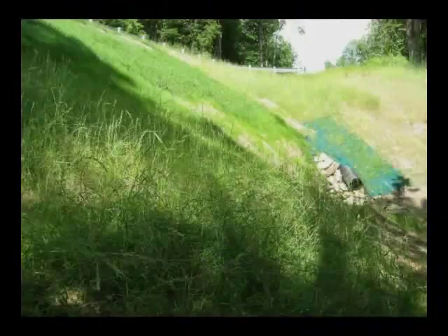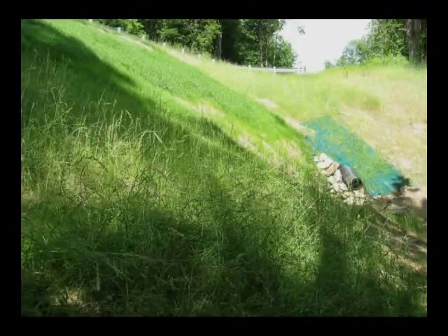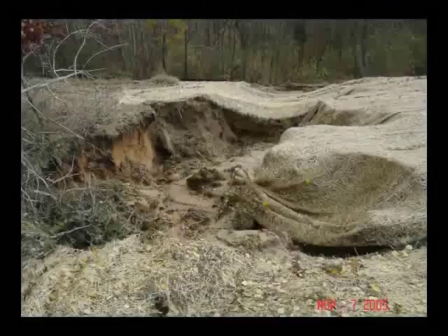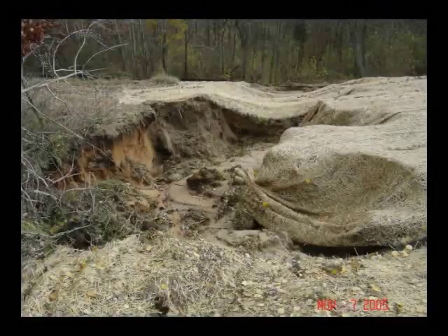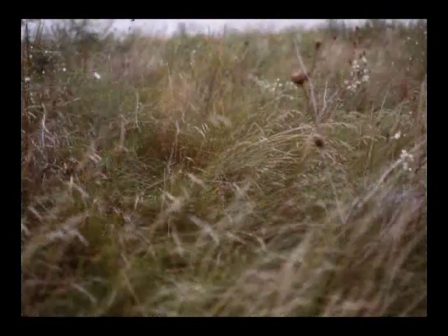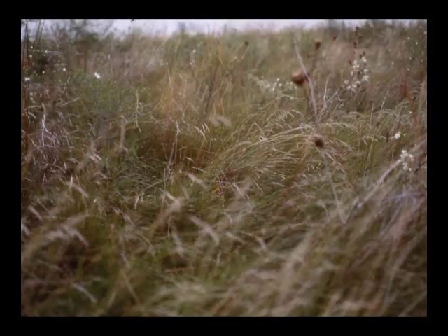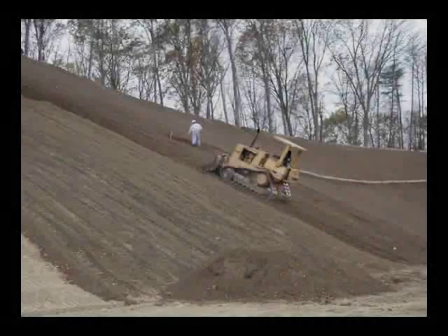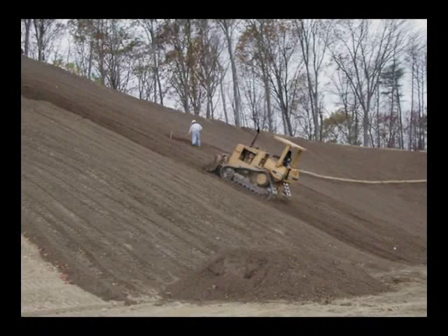The inspector should ensure that seed germination is adequate, coverage is complete, and that erosion has not damaged the substrate, seed, or mulch. He or she should verify that mulch or erosion control blankets are providing adequate cover to protect the soil and seed and are adequately anchored. Materials planted in the spring should be inspected during the summer or early fall so any necessary corrective action can be taken during the fall planting season. Areas planted in the fall should be inspected early in the spring so that maintenance can be performed during the spring planting season.